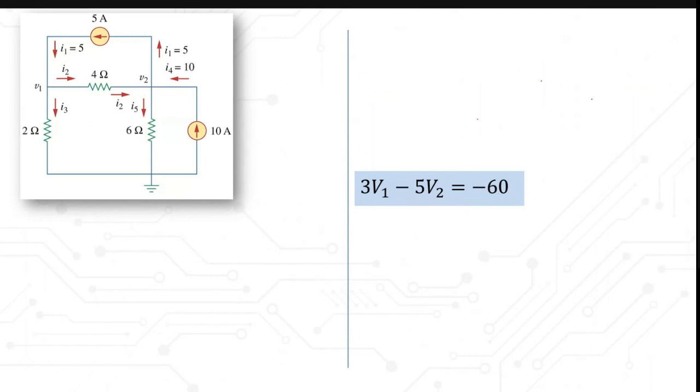Like I showed you on the previous slide, the first important thing that you need to know when you have this circuit is your current directions, because you want to do the summation of the current. The summation of the current entering the node and the summation of the current leaving the node, where positive is for entering and negative is for leaving the node.